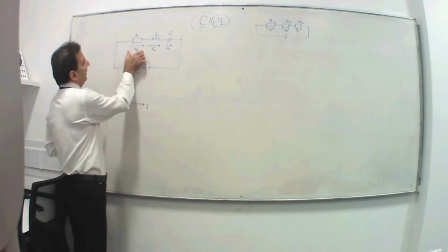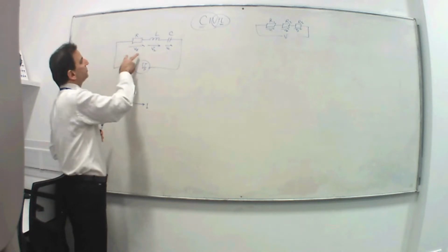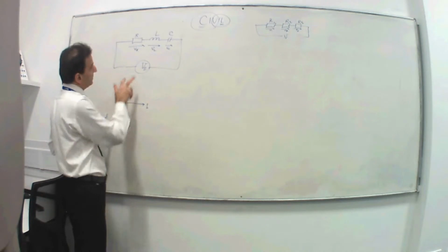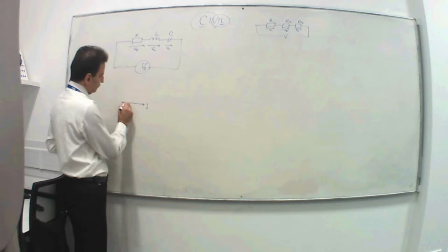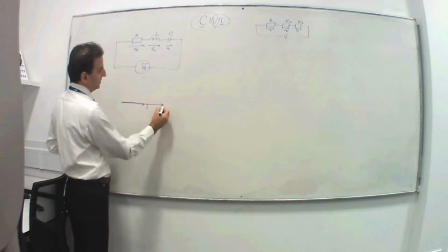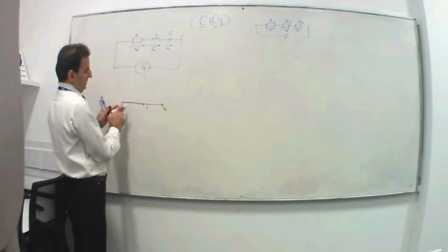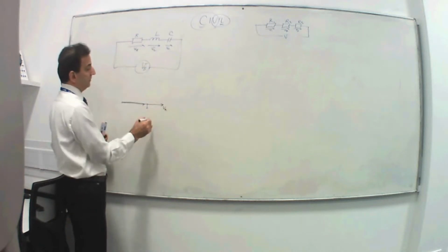Now, looking at the voltage of the resistor, we said if it is purely resistive, just the resistor itself, voltage of resistor VR would be in line with current. So I will just draw a line a little bit bigger than current. Like we said, voltage is usually bigger. So VR would be there in line with current, and that current is the current of the whole circuit.